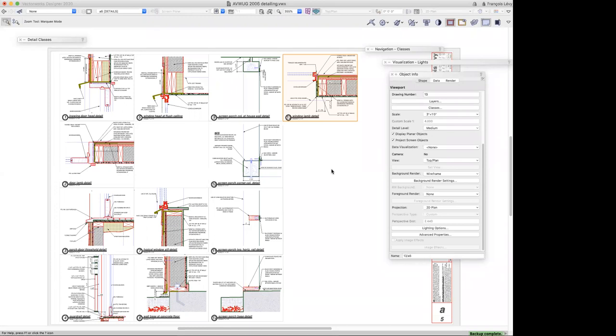That's one thing. The other thing is that, realistically speaking, everybody's different. Some people will hang on to Vectorworks for 5 versions and won't update, but we're updating Vectorworks every year. So if that sheet of details is 5 versions old and it's being referenced in a project that's 4 years old, updating the detail isn't going to retroactively update old projects, because that old project is referring to an old Vectorworks file that isn't being updated. And then finally, I always set up my viewports so that they only refresh when I manually refresh them. I never set up viewports to automatically refresh.